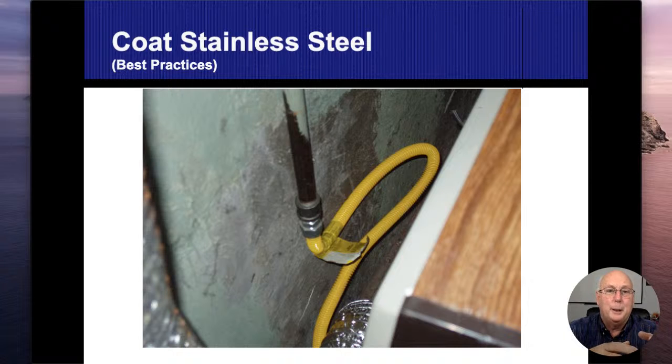So if they're close to a plumbing pipe or a grounded appliance or anything like that, then there ends up being a spark between the pipe and the appliance. And that spark, we're talking a lightning strike, so it has a tremendous amount of power. What's been happening is it creates a hole in that pipe about the size of a pencil, all right? But a hole the size of a pencil at 1/4 of 1 psi is pretty powerful.